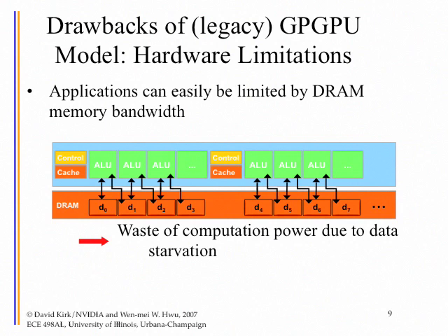So both of them need to go out and do the memory access. That's the reason why in most GPU interfaces, there's a little piece of hardware that looks at the traffic going by. Whenever it catches two accesses from different ALUs going into the same memory location in a very small time window, the hardware will try to combine them to save some memory bandwidth. That's called memory coalescing. Almost all the GPUs have that kind of capability.